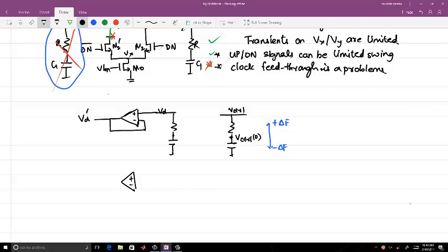The other case will be where you are saying I can bring C2, C1. What you are saying, can we do this? Right? This is the V control node, right? In both the cases, you can check that. No, the other thing is what you want to fix from this. You want to fix the dynamic range of the PLL. You do not want to change anything transient.